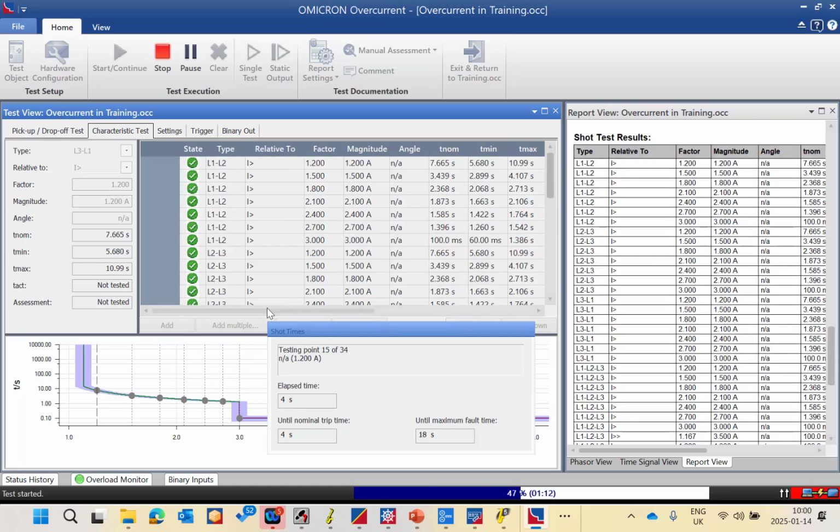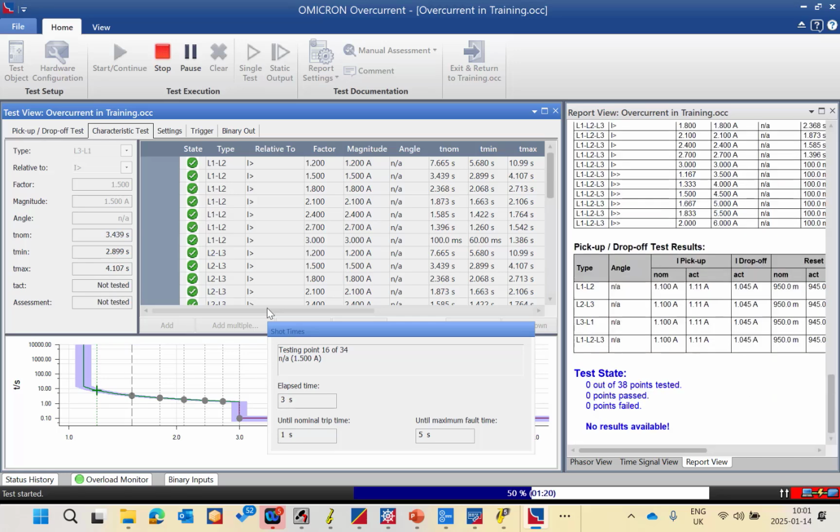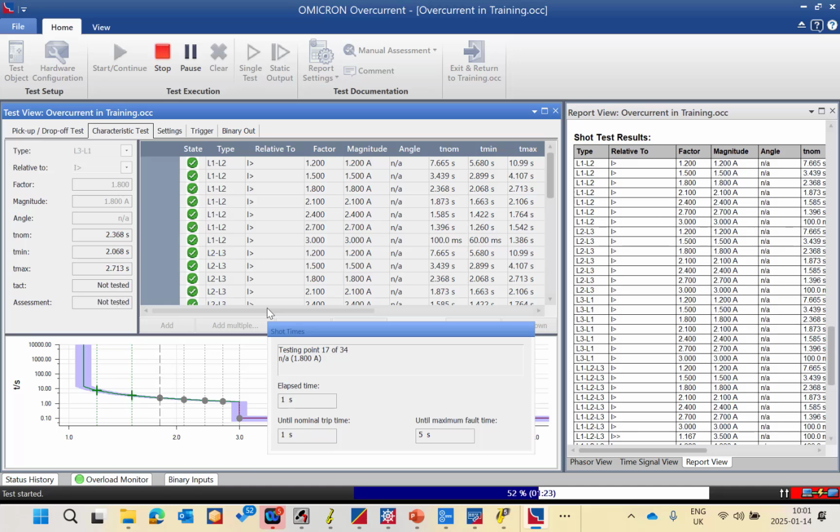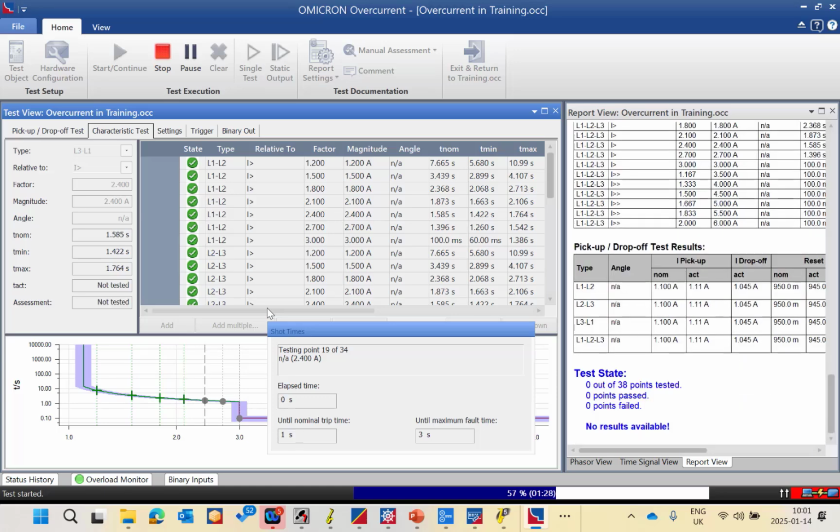So you have to check the relay technical specification, or if you are using the BTL, it's included already based on the relay manual. So with the BTL, no need to double check; it will be available, and it's matched with the type of protection relay.